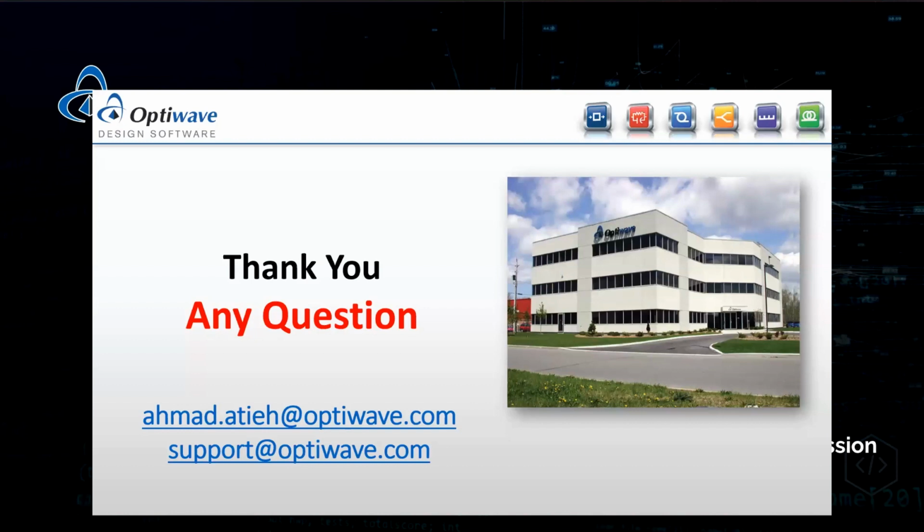How to design an underwater free space optic channel? The example which I showed you is an example designed in OptiSystem for an underwater channel. The best scenario is to take one of the examples using the free space optical channel in air, replace it with water, and then start to play around with the laser wavelength and the range, because the operating wavelength and the range are completely different between transmission in air and transmission underwater.